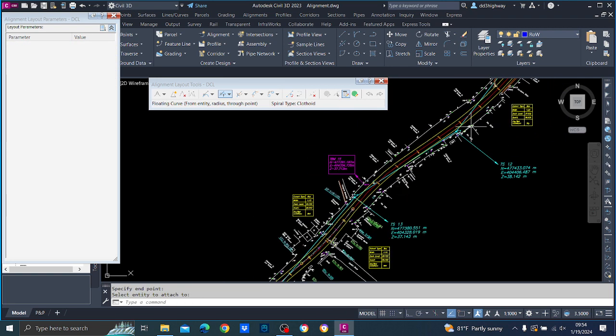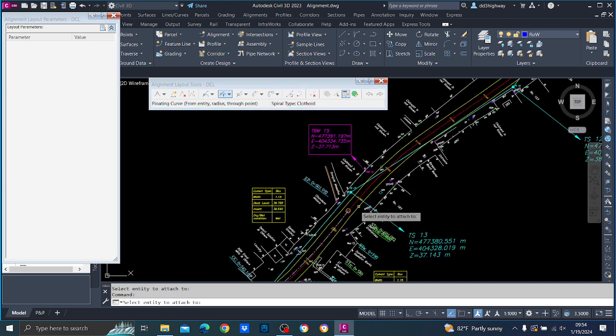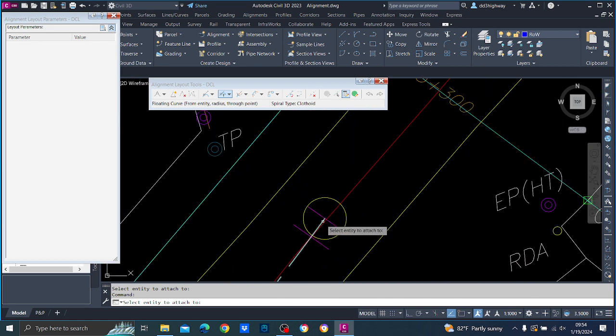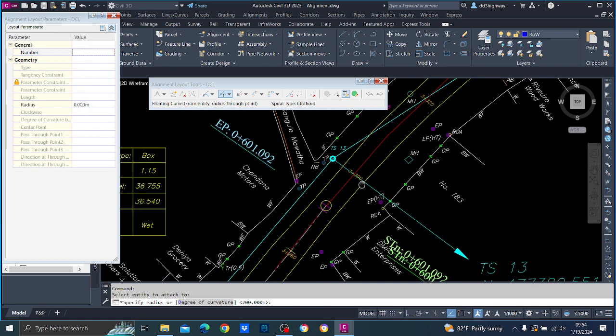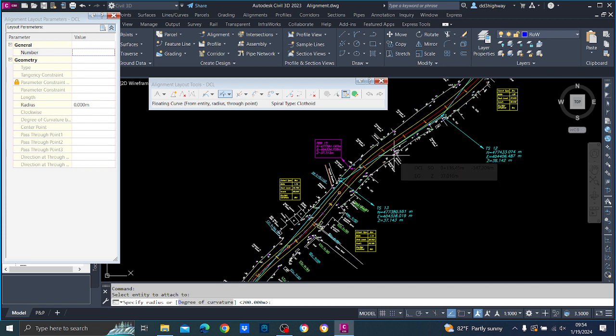And there's another curve. It's a sequence of curves. This may be again 250. Is this a good alignment? No, it's not a good alignment. We are not going this way putting curves and curves because we have to have straights in between. But unfortunately, this is a rehabilitation project. There is very little change we can do. So radius 250, less than 180. It should be reverse R.